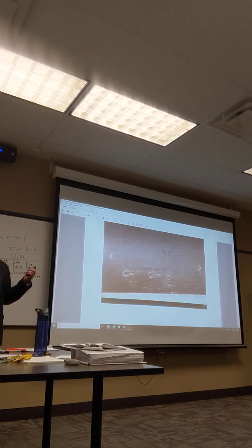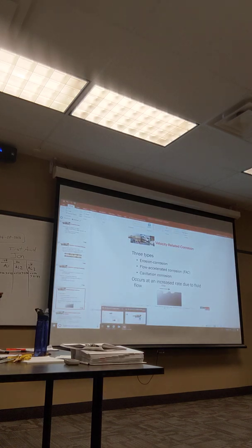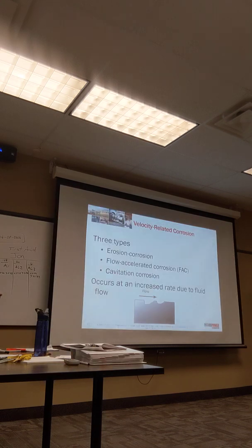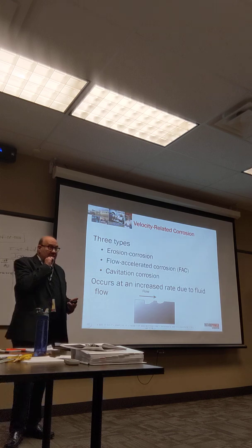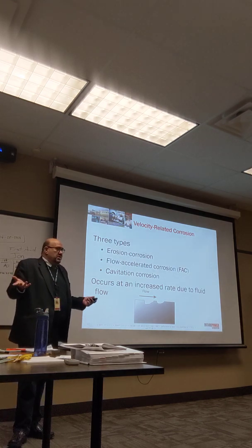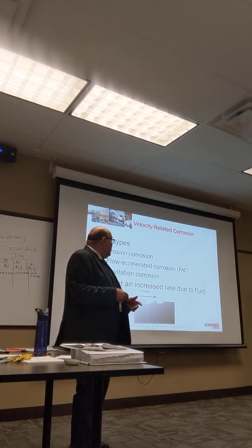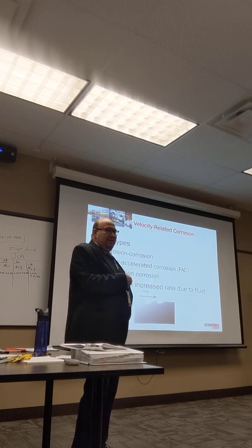This erosion is really happening because the velocity is just so high. The velocity is such that it's actually causing the copper to erode. You're just eroding it. And of course there is the corrosion type, because you do have the pitting.